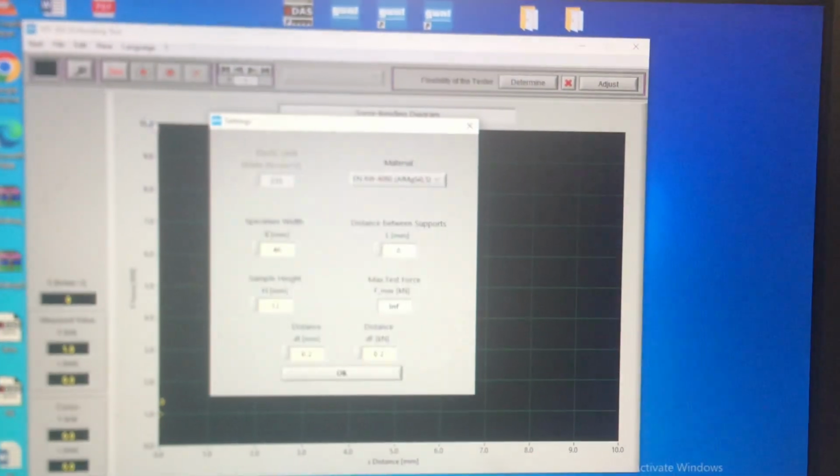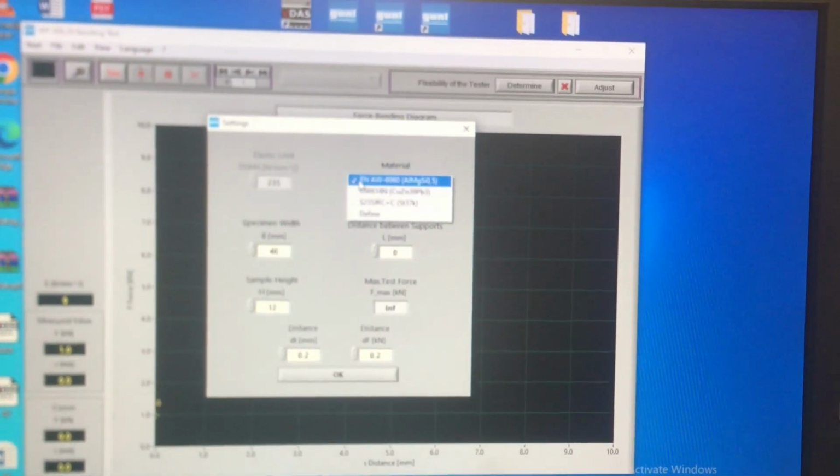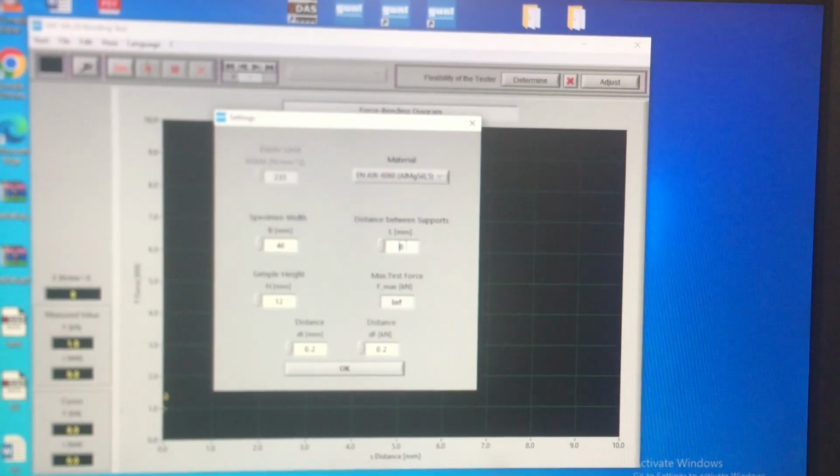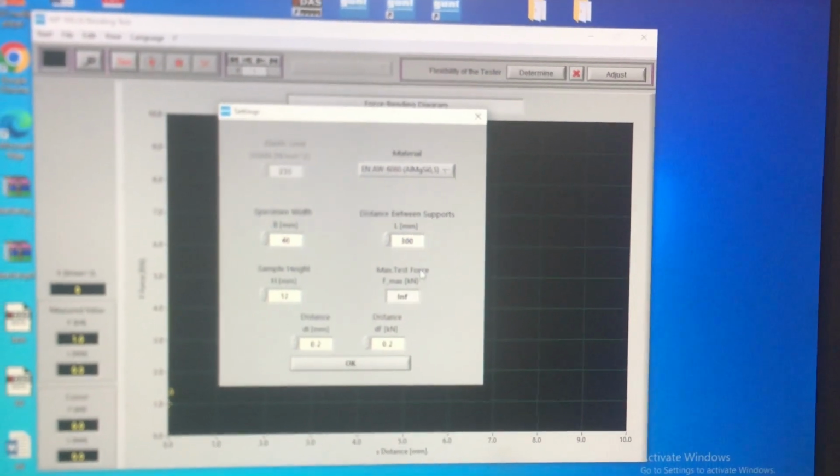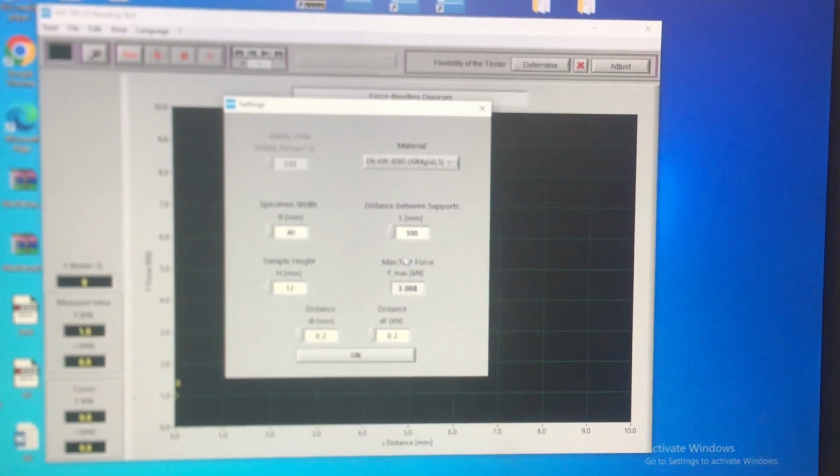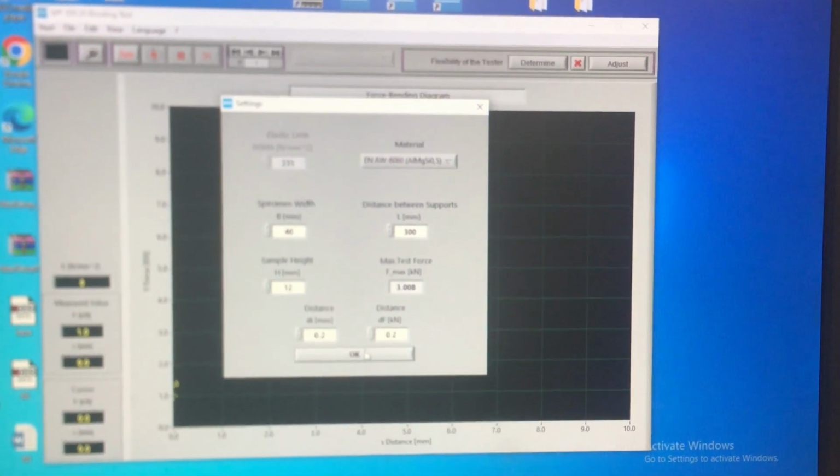In the software window, you'll have a graph with the y-axis and the x-axis. Within this graph, you will see a red line. Now this red line is your maximum force, which is also the critical elastic point. Beware that we should not surpass the red line, as it will disfigure the specimen, eventually breaking it.